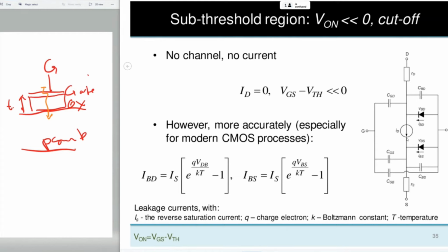As the transistors become many in number, statistically this small current that tunnels from the gate to the substrate piles up and can become a significant leakage current. This effect, by the way, is modeled in the dummy 45 technology that we will use for part B, our practical assignments. So you can observe it.